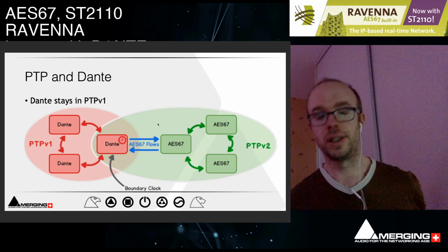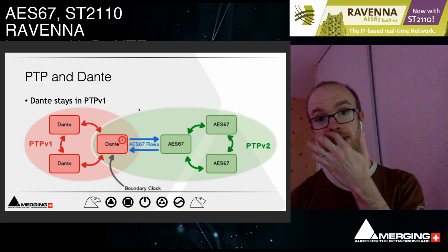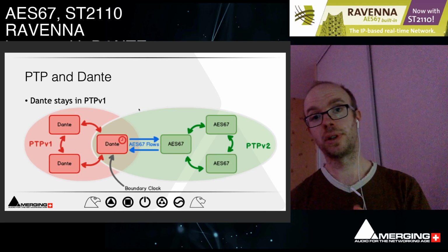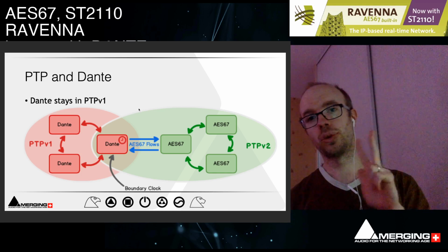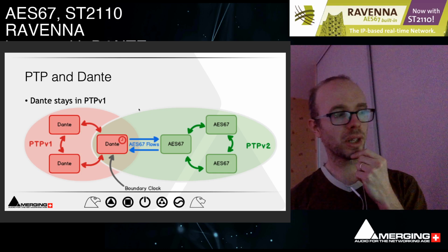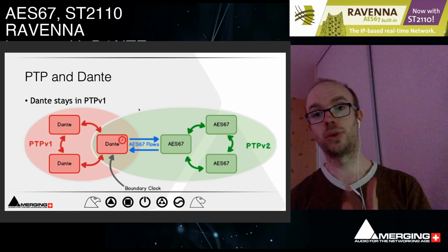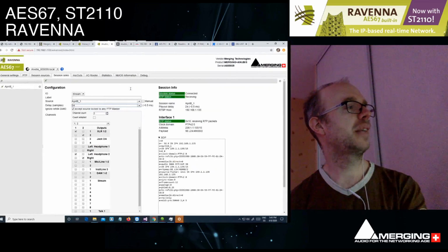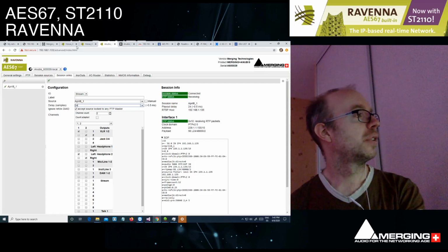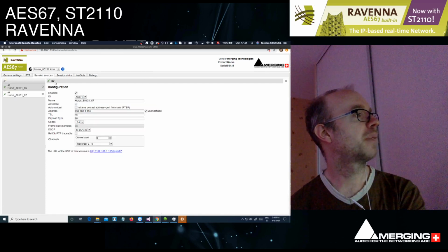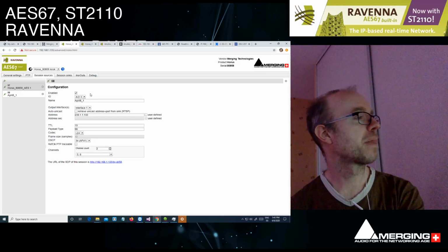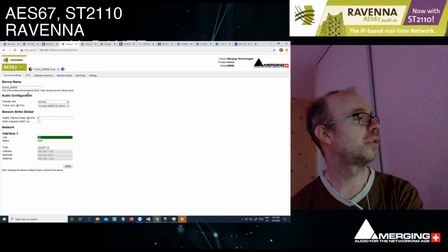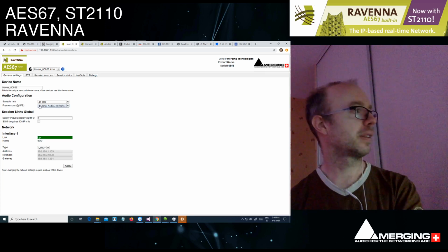Yes and no. So you have to have a minimum latency, and the minimum latency is actually 3 times, or 2. If you do the thing right, you can go down to 2, but the basic in AES67 is required to be 3. So you can go down to 3 times the packets. So it's not really a latency per se, but you see that I'm sending a packet from the Horus, which has 12 samples. So it's a packet of 1/4 of a millisecond.